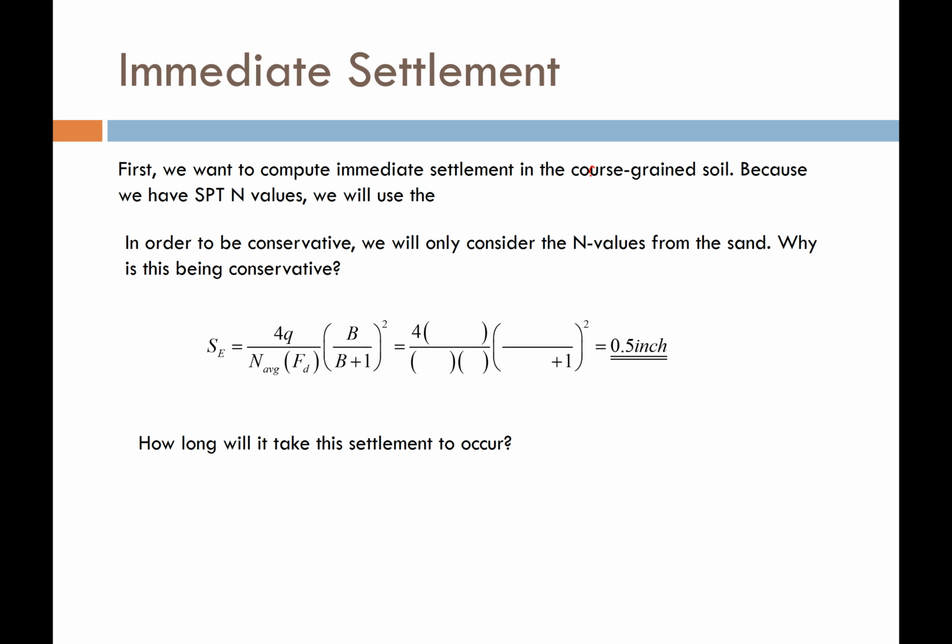There's the bane of my existence again. That should be an A for coarse grain soil. Forgive me, please. We're going to go ahead and use the Meyerhof empirical equation to solve this. Again, you could use whatever one you want, but you have to use the right equation based on the information that's given. And remember, what we are given is SPT blow counts, and so that's why I like this equation, because we can go straight to a solution.